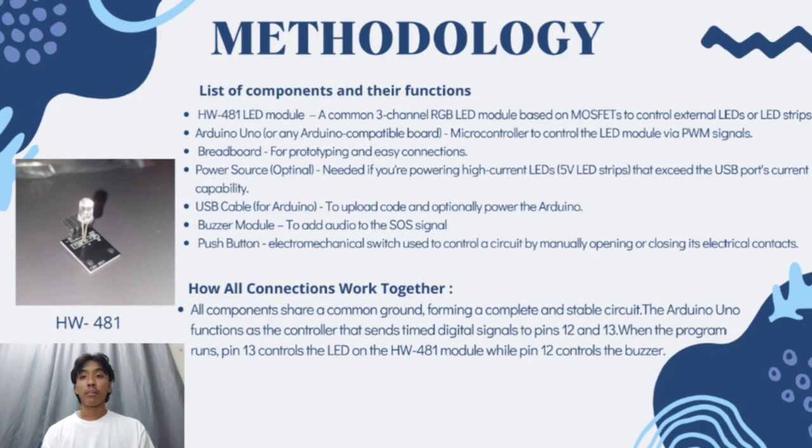We also added a buzzer module to produce the SOS sound and a push button to activate or stop the circuit. And finally, all components were connected with a common ground, and when the program runs, pin 13 controls the LED while pin 12 activates the buzzer, creating the SOS alert. So that's all for the methodology part.